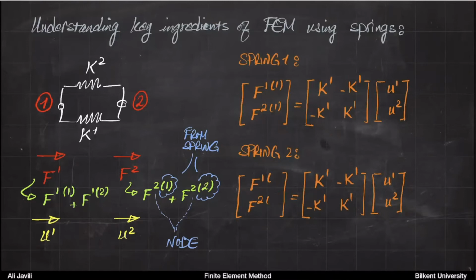So here, remember in the parentheses, we said the quantity tells you from which element. Now, this would be from element 2. And the stiffnesses, or the Ks, are the Ks of spring 2, but the U remain the same U, okay, because it's for the system. All right, so we have this thing so far.